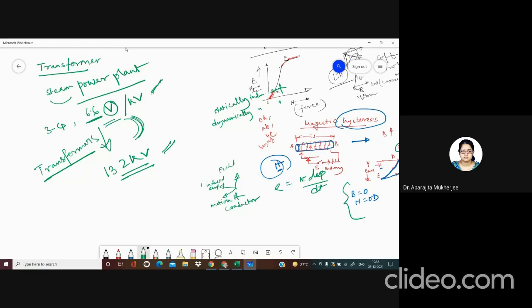আচ্ছা, এরপরে কোনো জায়গাতে বা বাড়িতে আমাদের কি লাগে? কত ভোল্টেজ আমাদের বাড়িতে জানা আছে? বাড়ির যে আমরা একটা সুইচ মারলাম, সেই সুইচের আমাদের স্পেসিফিকেশন কত? হ্যাঁ, 120। না না না, ওটা ইউএস চলে গেলি তুই। এখানের কত স্পেসিফিকেশন বলেছিলাম আমি প্রথম ক্লাসে? ম্যাম 220। 240। ওকে, ওকে 240। সো 240 যে ভোল্টেজটা, এই 132 কেভি থেকে আমাকে কোনো একটা ভাবে 240 ভোল্টে আনতে হবে। কে করবে সেটা? ট্রান্সফরমার। ডাউন। কি ডাউন? স্টেপ ডাউন ট্রান্সফর্মার। সো দিস স্টেপ ডাউন ট্রান্সফর্মার এনার্জিটাকে ডাউন করছে। কোথা থেকে করছে? প্রাইমারি সার্কিট থেকে সেকেন্ডারি সার্কিটে করছে।